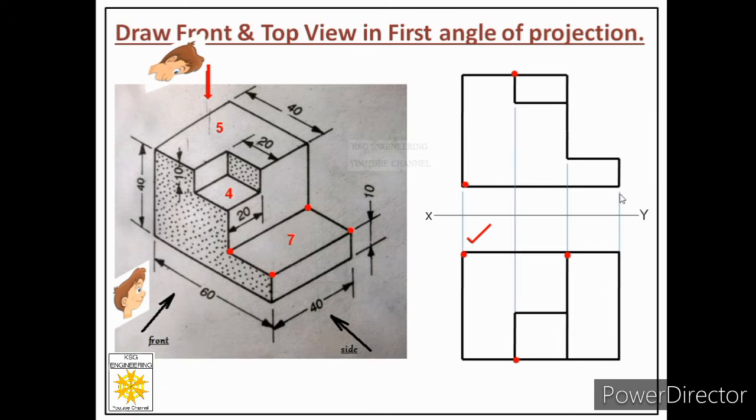These projections will lead you to this edge or this line. So this is the front view of this face. You can see this edge is over here. Fine. So like this you can relate the front and top of a particular plane. This will help you to find whether your front and top are correct or not.